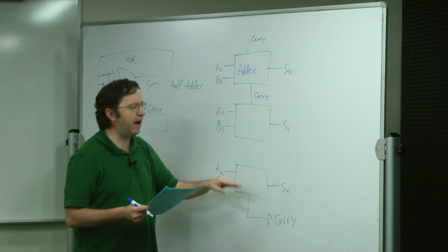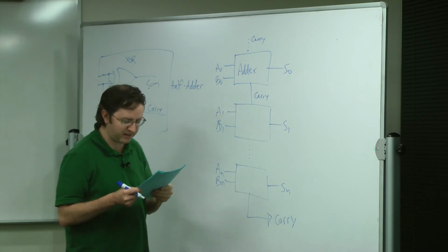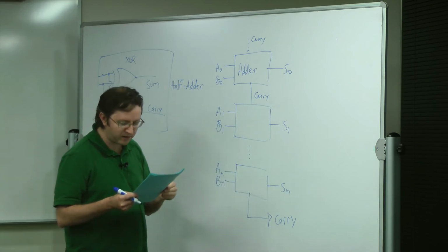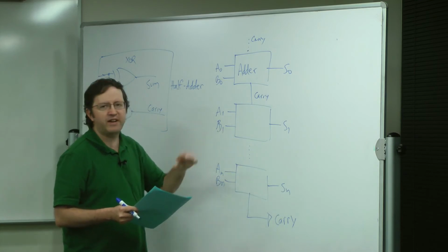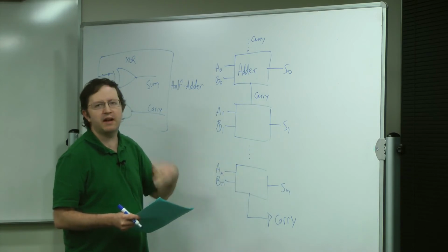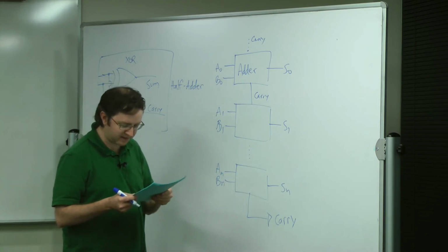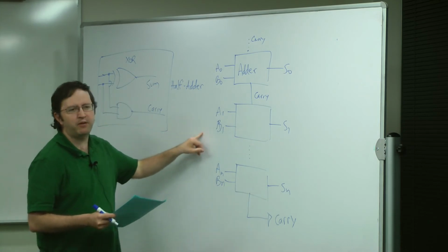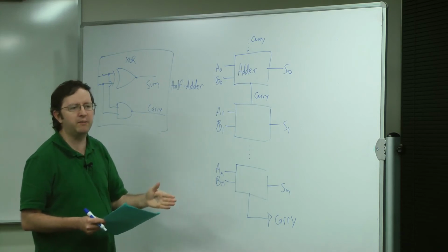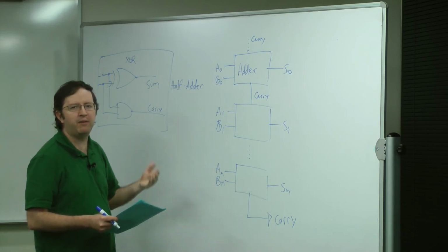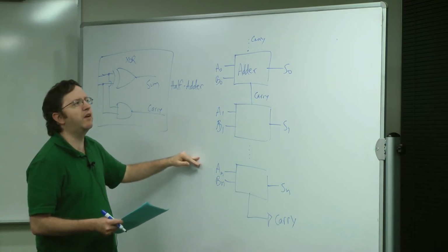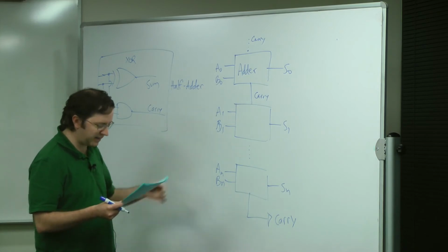And there are also optimizations for the carry, such as something called a Kogge-Stone adder, or a carry look-ahead adder, or a carry save adder. And they all use various techniques to try to parallelize and otherwise help to speed up the addition process. And the adder is also important because it makes it possible to do calculations to figure out where you might want to jump ahead in code, or how to increment the code pointer or other things like that.